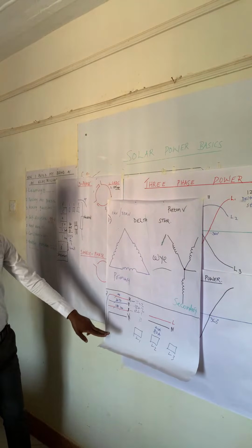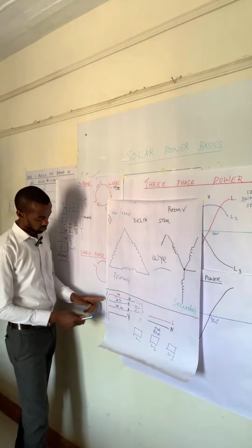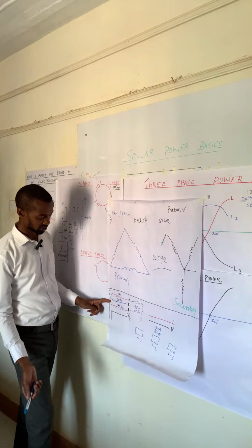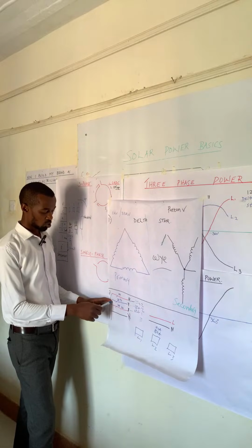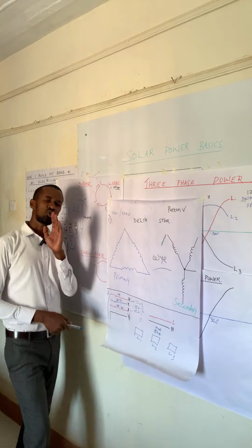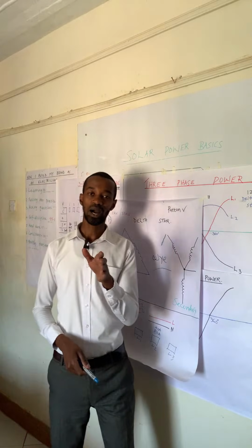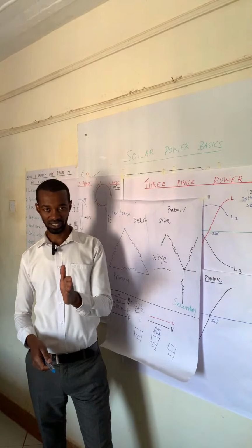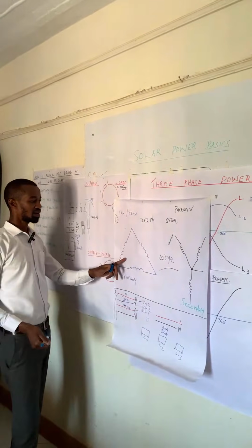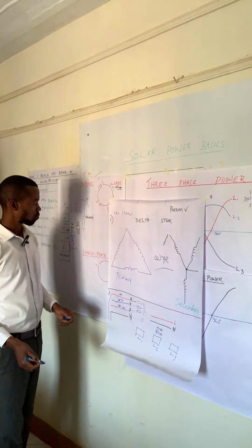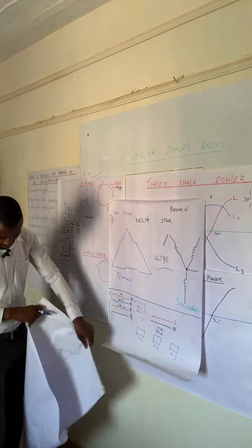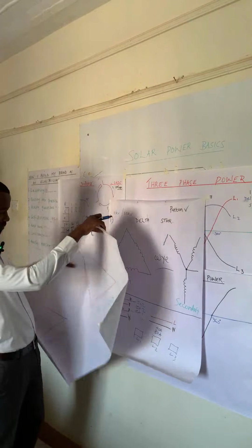How do you achieve a single phase connection? Like we have said, you just tap one of the phases and neutral, and feed that single phase customer. That is how you connect a single phase from a three-phase distribution. Can you connect a customer who requires three-phase connectivity from a single phase? Remember, we can also have another power distribution where we have a single phase transformer.